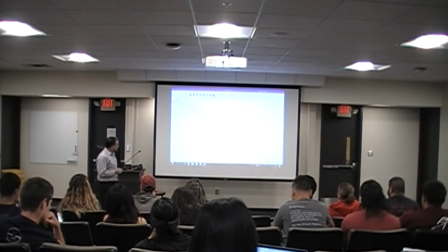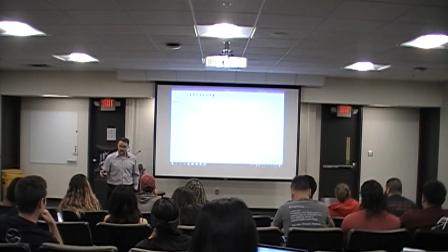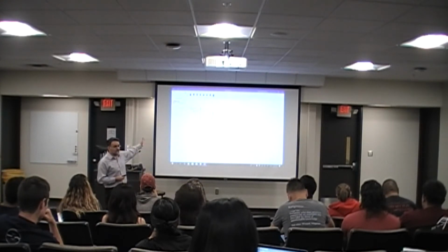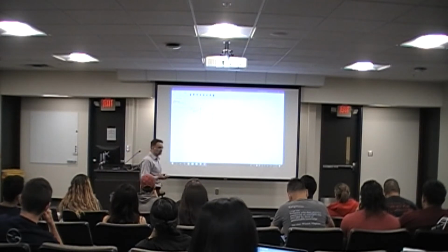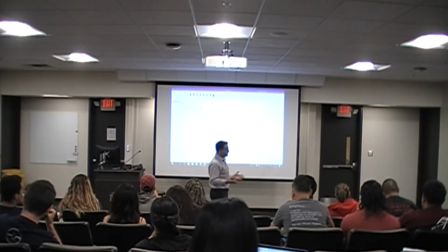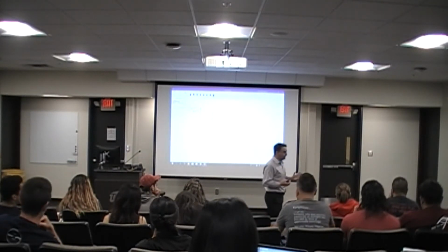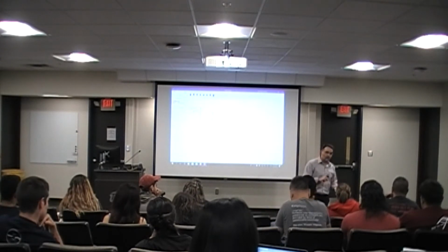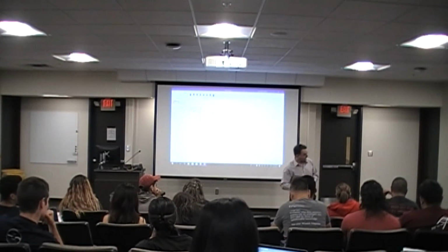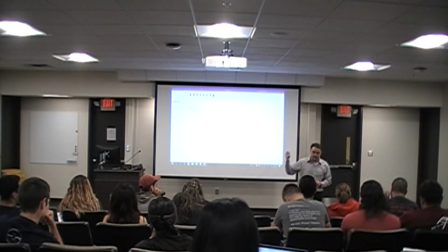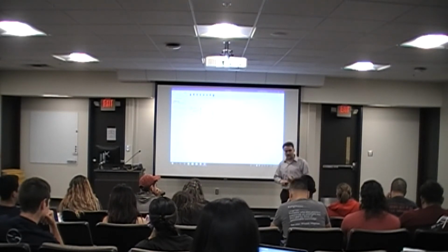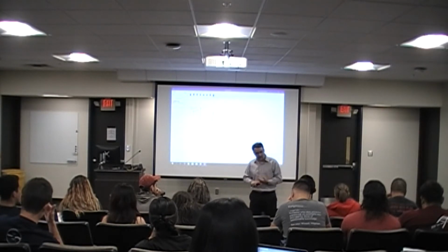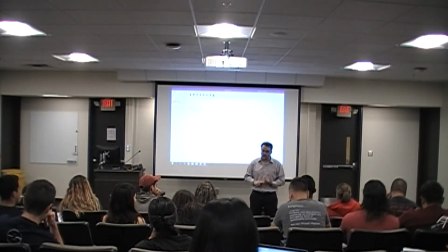Now, the second part was getting the strength of the material. The strength of the material is that peak that we have here, that tau sub F. Calculation or determination of the strength of the material. How did we determine that? Remember, we go to the lab, we run the direct shear test, we run the triaxial shear test, and get that tau sub F, right? So up until this point, we know how to calculate the stresses. We know how to determine the strength of the material in our stress strain curve. What is left?